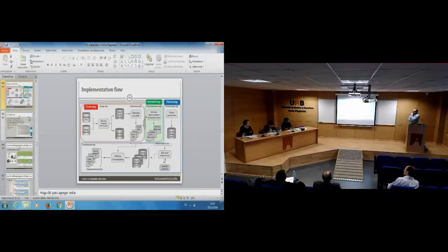Are they really specific for TFTs, or just SPICE 1, SPICE 2 for silicon? Because you mentioned about the models that were used by people, but the many kits that was like this, just basic MOSFET model. But in your case, which model did you use for the simulations?